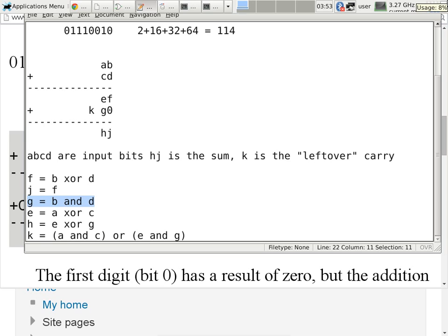This carry is automatically the carry to the next digit already, because when you look at the equation, F is going to be added to a 0, which guarantees not to have a carry of 1. So the only possibility of having a carry of 1 is B plus D, and that is already going into the carry in of the next full adder.